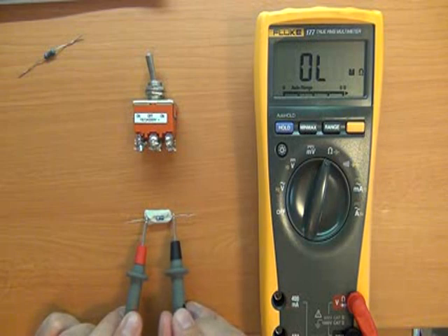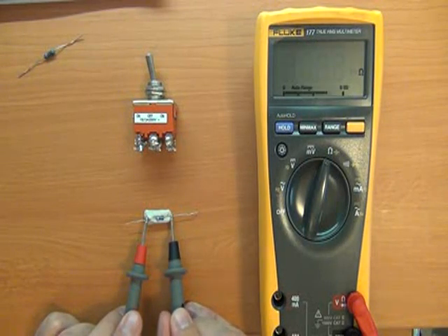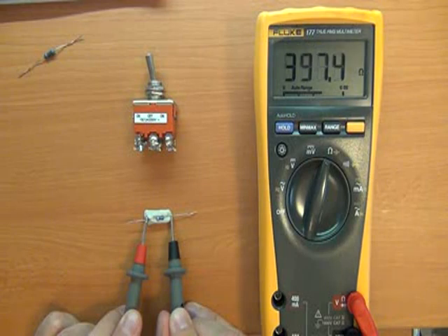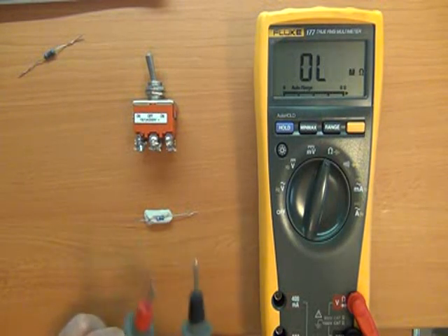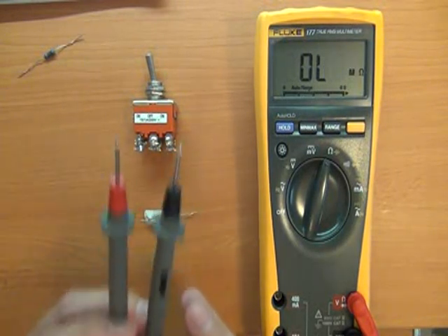But here we go. We put the two probes on either side of the resistor. I just have to push down to make sure we get a good clean reading, and there we go, 390.3 ohm. Again, remember, this is a 390 ohm resistor, but that 0.2, 0.3 at the end is potentially the resistance which is sitting in your leads.